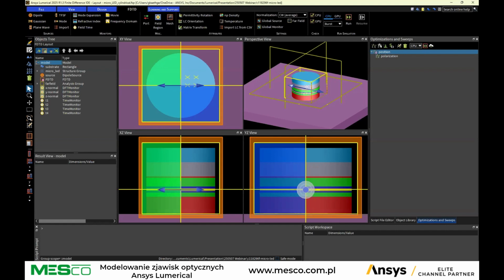Things that can help to speed up the simulation are parallel computing or high performance computing. The way we run the simulation, if I just wanted to run that simulation, I could just click the run button, which has different options. I can run on CPU, I can run on GPU. My laptop has a small GPU, so I could run that on my laptop on GPU.